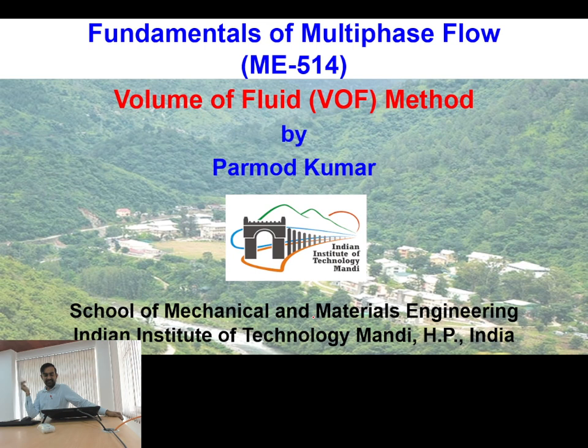Okay, so in yesterday's class, I mainly explained the interface evolution in a one dimensional system, and then we initially started the discussion on two dimensional systems, particularly how volume of fluid ensures the conservation of mass. That is something which I have discussed. Now I will discuss 3-4 methods which can be employed for reconstruction of the interface. What are the issues with these methods, and what are the advantages of one over the other, I will take up in this.